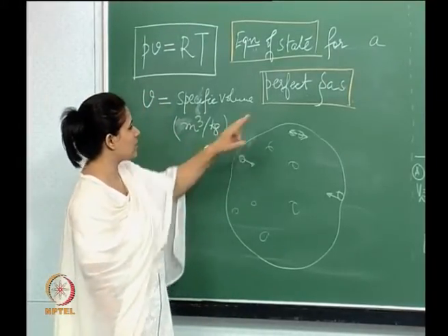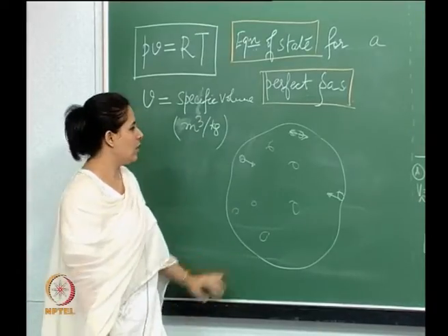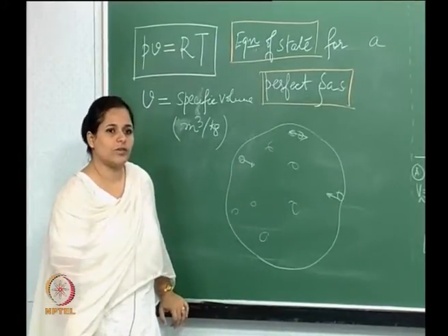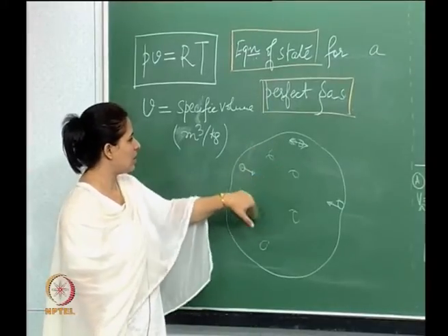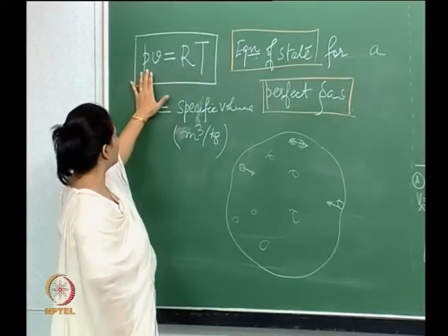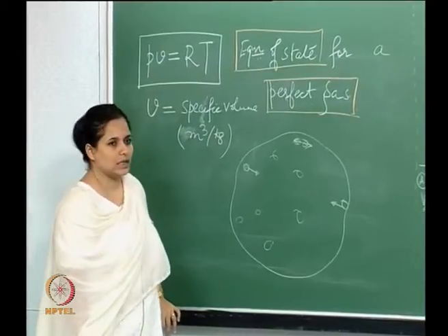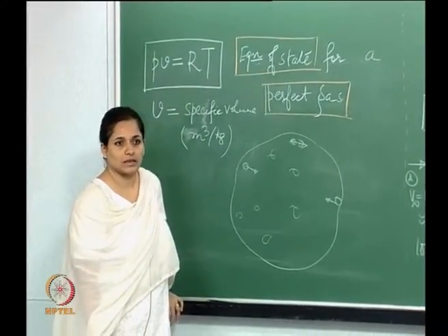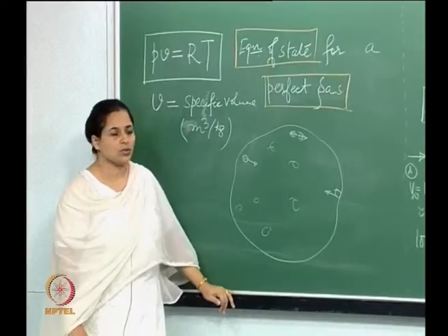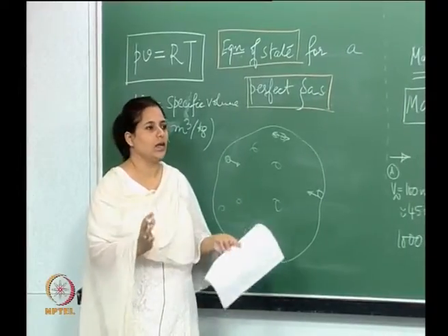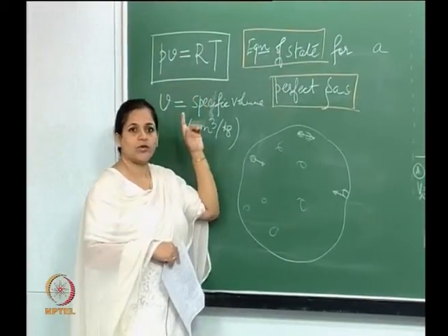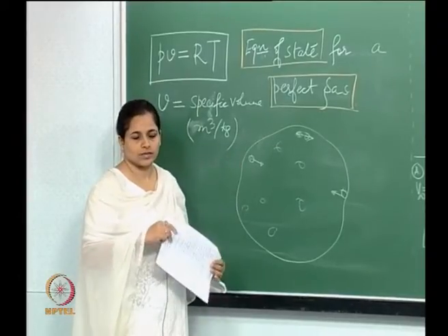Now, the thing is, what is this perfect gas? The perfect gas is one where we ignore these intermolecular forces. For a perfect gas, when we ignore these forces, there is a certain relationship between the pressure, volume, temperature, density, etc., of that gas, and that relationship is what we define as the equation of state. Which means that if I have some mass of gas, then that will obey this sort of relationship, provided we ignore the intermolecular forces, right.